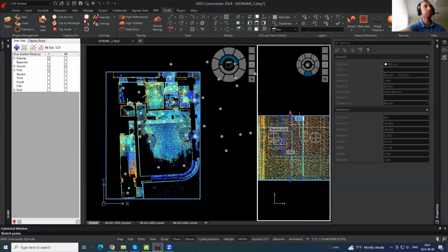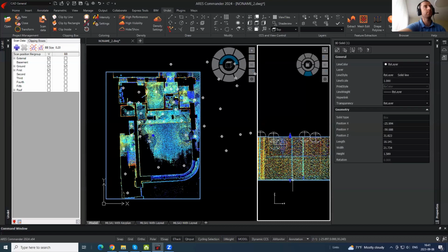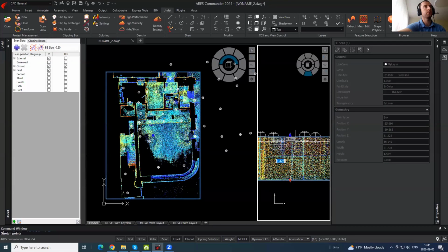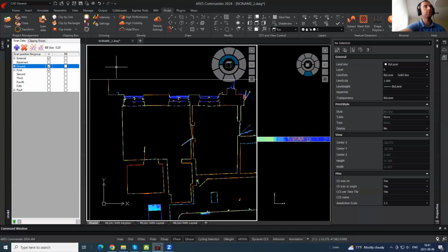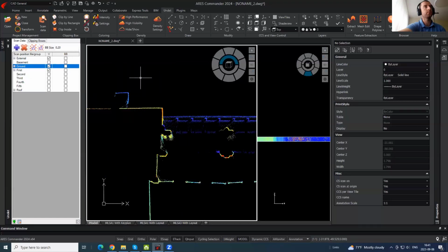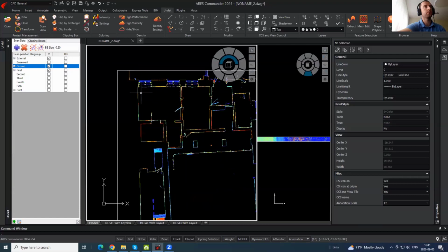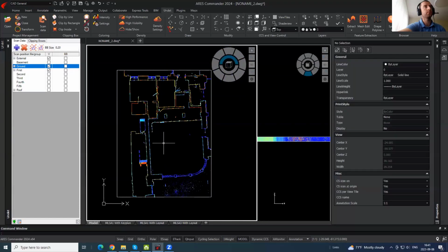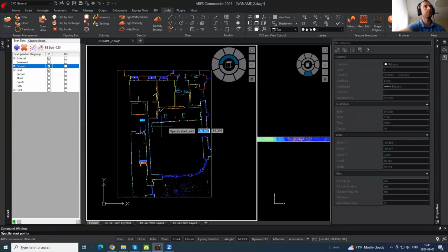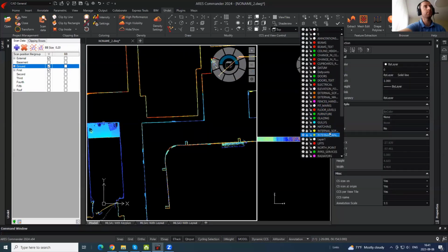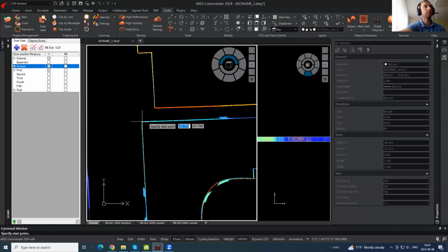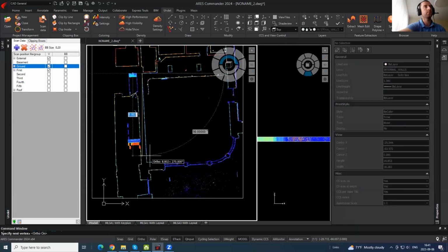I'll make a section cut at about 1.5 meters around the building, and now I see an accurate floor plan, but it's still not vectorized. I need to vectorize. First of all, I find a long wall and draw a direction of it to catch the angle from one corner to another.